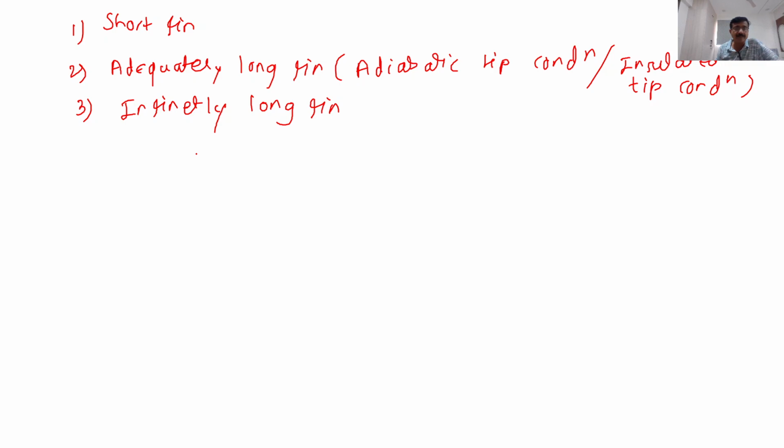And the third case is infinitely long fin. In that case, any length which is greater than the condition of adequately long fin is called infinitely long fin. So in most practical applications, the fins are designed on the basis of the second condition, that is adequately long fin.